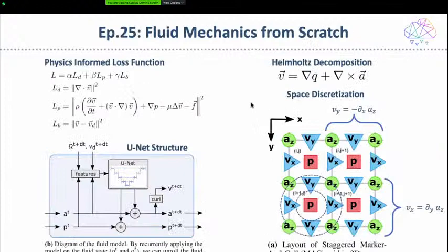And two episodes ago, we looked at a very different approach, which isn't directly a physics-informed neural network, but it's a slightly different approach. However, we still use this physics-informed loss function, which describes how well the network meets the equation, which in this case is the incompressible Navier-Stokes equation. Then also the incompressibility, and also some terms describing the initial, oh no, sorry. So basically the terms: the incompressibility, the Navier-Stokes equation, and the boundary conditions.